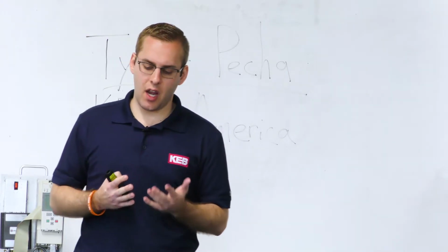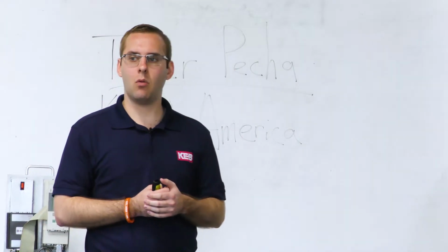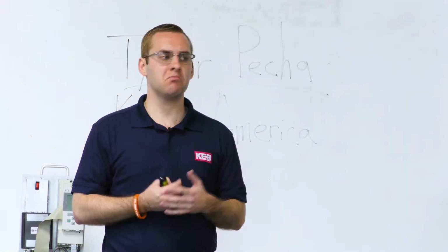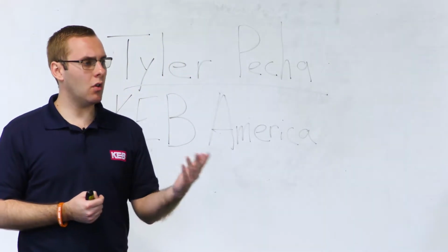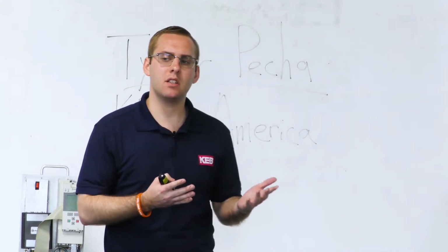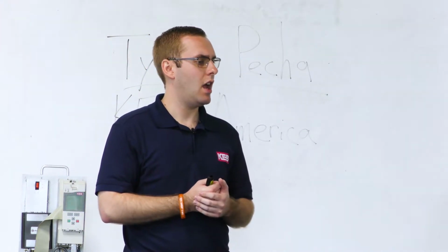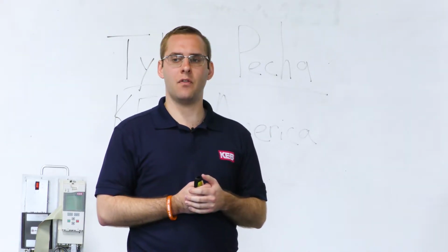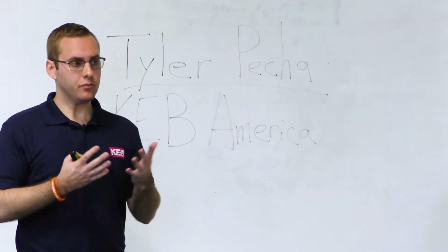So that is one thing to look at. To see if it could be a potential sizing issue, you can play with the accel rates. Try decreasing your accel and decel rates and see if the problem is still there or if it goes away. If it goes away, then it could be something with the size of the resistor that may need to be looked at. If you're getting it regardless, then maybe the resistor itself is bad, or the drive itself, the braking transistor, could be faulty.